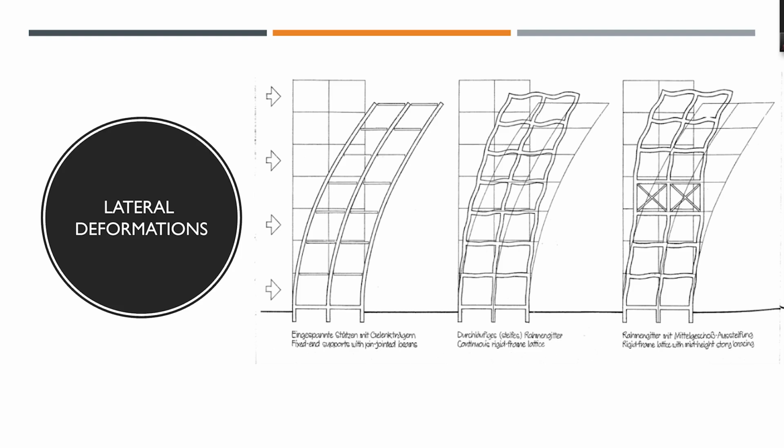And this is the lateral deformation, so it's a little bit more clear. You have this way, which is basically that the joints are not working. Each column is independent. When you connect them together, it becomes like a frame, so you have bending moments and deformation relating to that. This one, if you brace it, becomes like this. So it's a very clear diagram of what happens if only the columns are working and the floor beams are not working, like a flat slab. A flat slab will be like this.